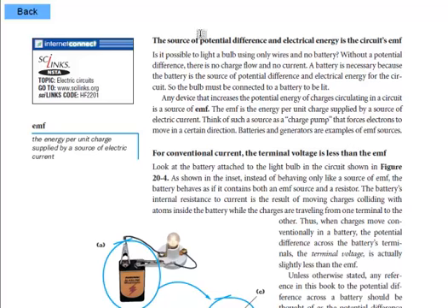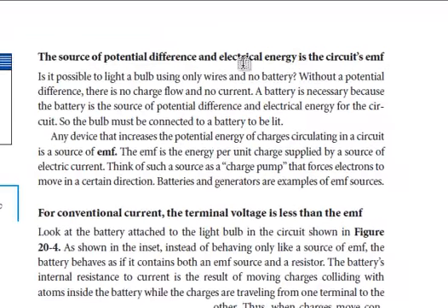You should know the difference between what we call the terminal voltage of a power supply versus EMF. Very often when we're talking about batteries and generators, we focus on the idea that they provide the potential difference to allow charges to move through a circuit. That value, a 9-volt battery, a 120-volt outlet, is called terminal voltage. This is the amount of potential energy per charge lost going through the circuit. This is the rating on your battery.